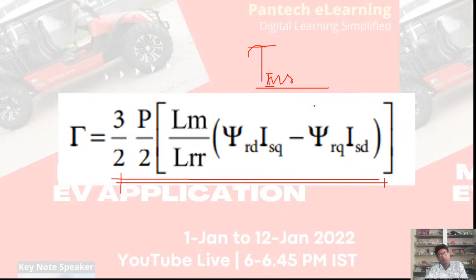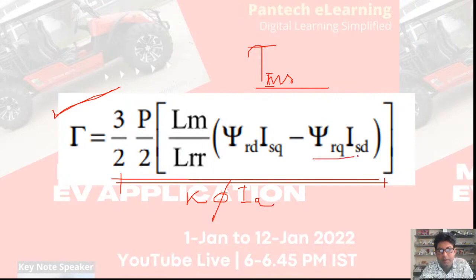Already I gave you a glimpse of vector control: it is nothing but converting the torque equation of the induction machine to be analogous to a separately excited DC machine, which is nothing but some constant into some flux into the armature current. To do so, I have to vanish this.